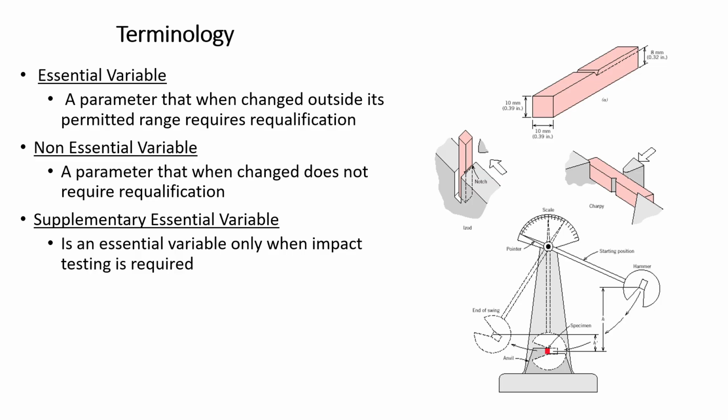A supplementary essential variable, we're talking about impact testing. And this is a Charpy impact test right there. So if we're talking about changing a variable that is going to affect our impact strength of our material, it becomes an essential variable.